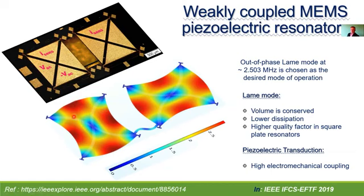I have chosen the Lame mode because in this mode, the square plate extends in two directions and contracts in the other two directions, because of which the volume will be conserved when the MEMS resonator operates at this mode, and higher quality factors can be obtained when the square plate resonators operate in this mode.